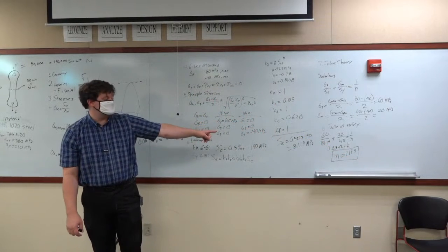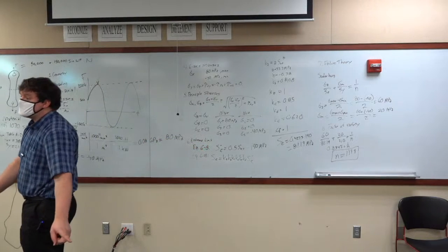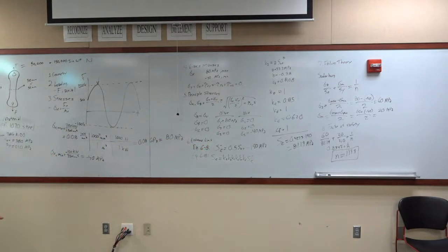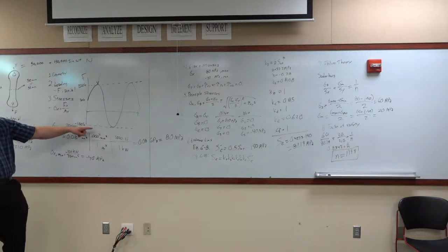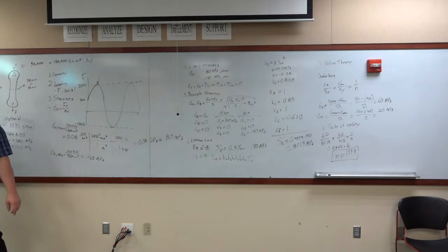And we're predicting this is going to last forever. If you have any variations in the loading, though, if your loading gets any higher than that, you're risking failure. If the loads are any less than that, that's fine, so long as you don't happen to go below 100,000 loading in the other direction. That's a different story. Okay?